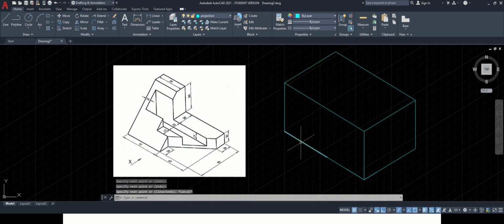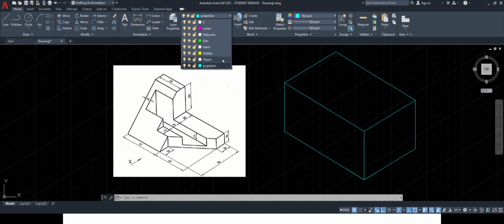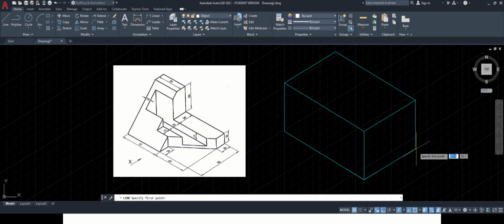So this is the front plane, side plane and top plane that is visible to us. Now the first thing I observe when I see from this side is this 20 by 20 square. I can switch on the object line layer and draw that square of 20 by 20. Type 20, enter, towards this side 20, enter, downward we go 20 and towards the right again 20. So this box that was visible to us, we have drawn.